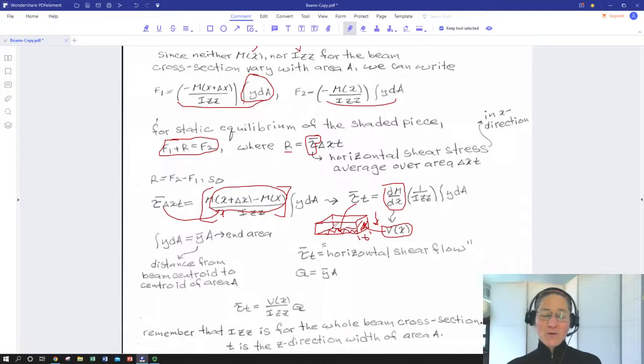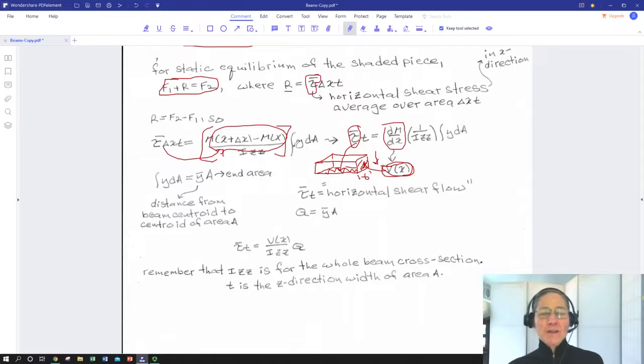So we're going to relate some shear stress on a face that has a y surface normal, heading in the x direction, to what's going on the x face, where we're looking at a force going in the y direction. That's symmetry of the stress tensor. So we can do a tau yx, which is what this is, related to a force that originates from a tau xy. Fair enough.